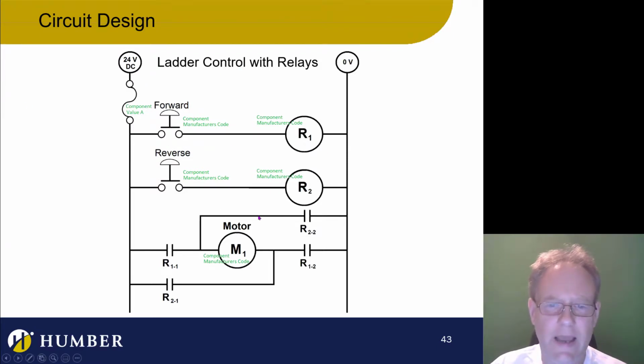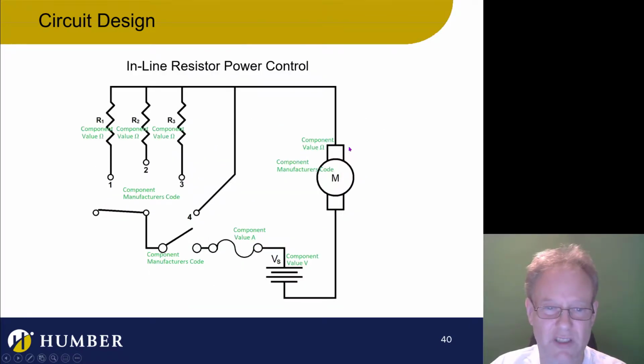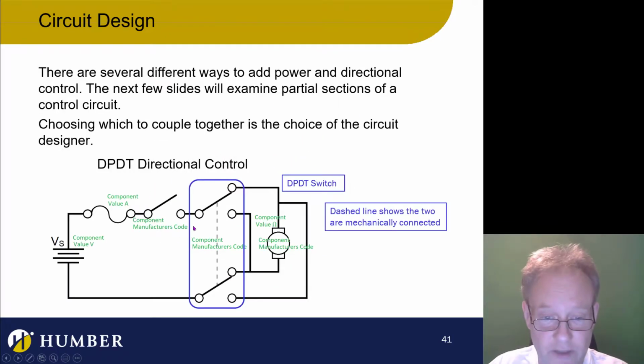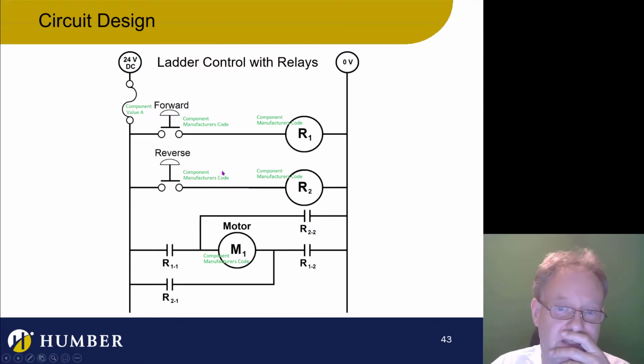Now, if you are doing ladder logic for your design, because for your assignment, you're going to have to choose this, because it's the only option. You can put this in however you want, but you're going to have to choose either this type of control, or relay control. If you do relay control, I would like to see a safety interlock. Put that in, because it's important, because it's safety.